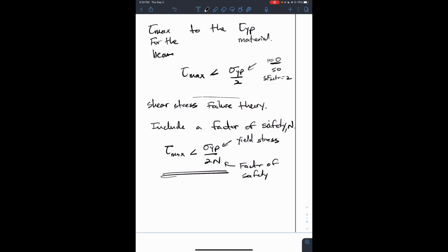Standard we use 2, so it's usually about 2. But if it's dynamic loading, for example, if people are throwing tools into this basket as opposed to resting them down, then we could go up to about 4. There are tables and charts that I will cover in a lecture that govern this.